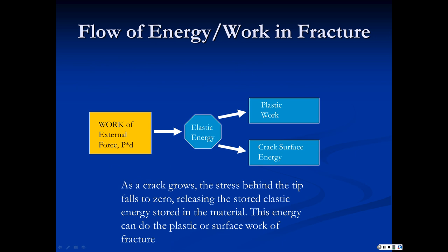Now, again, to go back, understand that in fracture, the work of fracture is done by some external force acting on the structure or your specimen or whatever. And we can measure the amount of work done by measuring the force and measuring the displacement, and the product of those, or the integral of those, if one of them is not constant, is the work of that external force. So we find the area under the load displacement curve, and we have that work that's input.